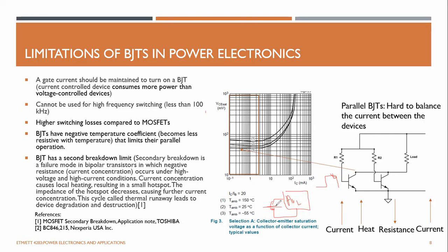If you use a MOSFET, you can maybe use the same battery for your Arduino for 1 month, because MOSFETs are just voltage-driven devices. They don't need to drive any current, right? So it's more efficient when you're using a MOSFET compared to BJTs. BJTs require current, so it leads to low efficiency.